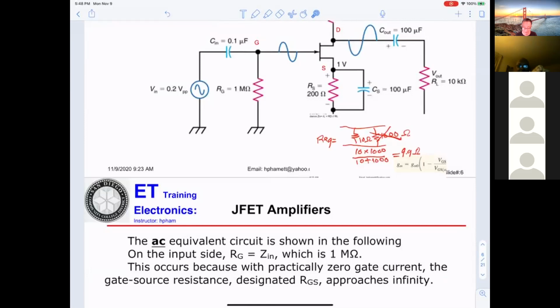The only thing I recommend, when you see the circuitry, is that you must know this is a common source JFET amplifier. Input and output will be opposite, or out of phase. That's why they show it right here: that's the input and this is the output. That's the only thing you need.